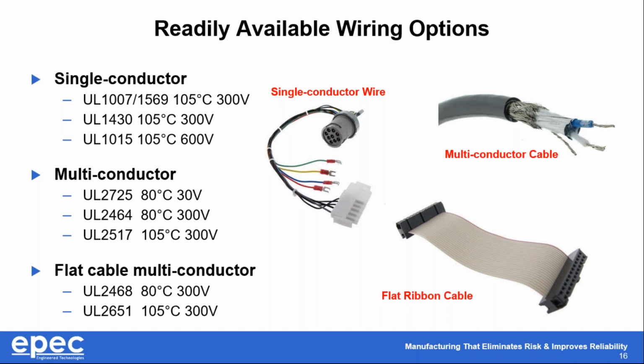Another consideration when looking at readily available wire options is to make certain that the temperature ratings and voltage ratings align with your program needs. Each one of these unique wire types is designed and qualified up until those thresholds.